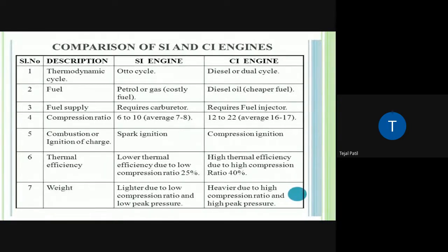So it would definitely be good if you could do the auto ignition, because the power required for the spark plug would not be required in that case, right? But if you are using it in the petrol engine and raising the pressure very high, before the power stroke it will start burning, and that means complete combustion will take place before the requirement.